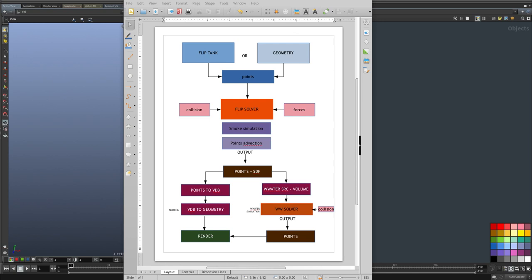And then once we have these two things, we're going to feed points to the flip fluids. That's the main idea. We're going to feed it points, and then it's going to use those points and move them to mimic the water behavior. Now, as we all know, water is incompressible, so it doesn't lose volume and it doesn't add volume. And solving the incompressibility feature or the pressure equation cannot be done through points, because points are just sparse. And to solve anything that is basically a fluid-like behavior, where we need to keep the pressure consistent in a certain domain, we're going to use voxels for that.